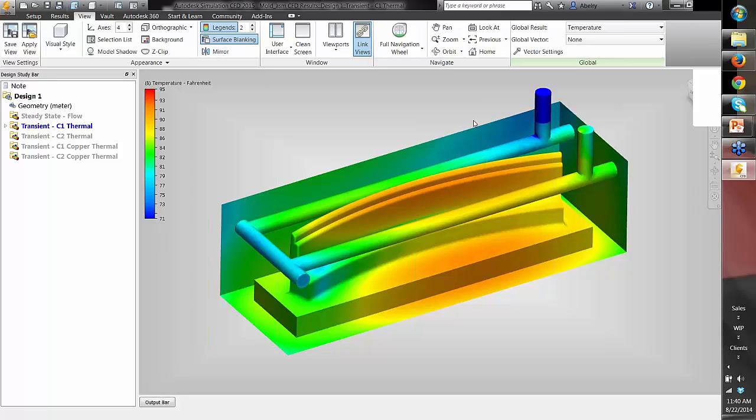And it makes sense to use CFD if you're not familiar with Moldflow. It's an easier tool to pick up and learn how to do thermal analysis. CFD is used in a lot of flow and thermal studies, and conformal cooling is a very challenging thermal study. You don't get it right the first time, or the second time.